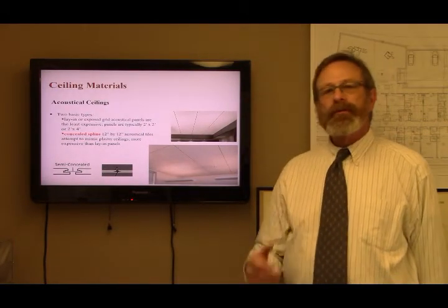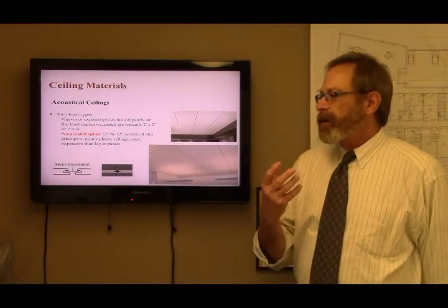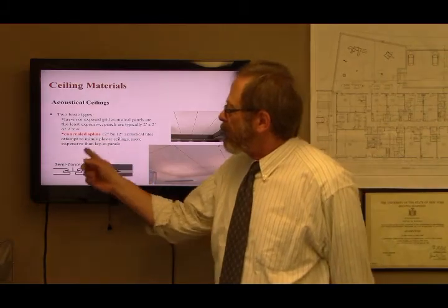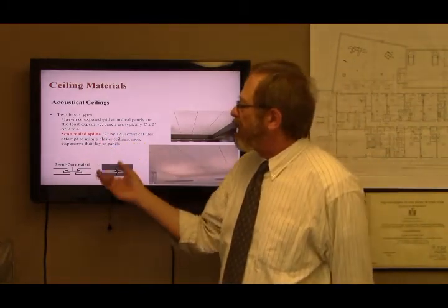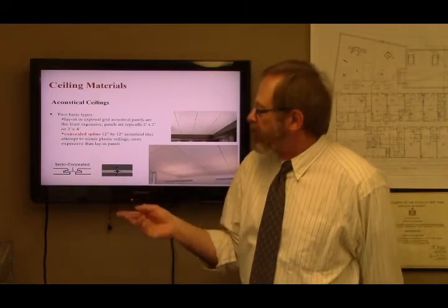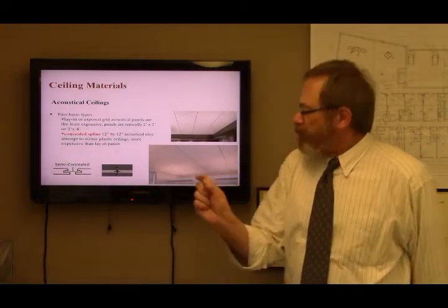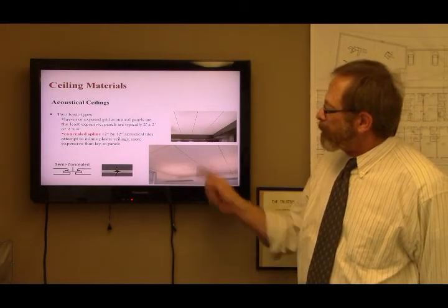So those were splines or joints of grid that were visible to us, and the one that I just referenced was a concealed spline, not supposedly visible to us. Then we have semi-concealed, where you can actually see just a portion of the grid system. It gives you a little wider gap.